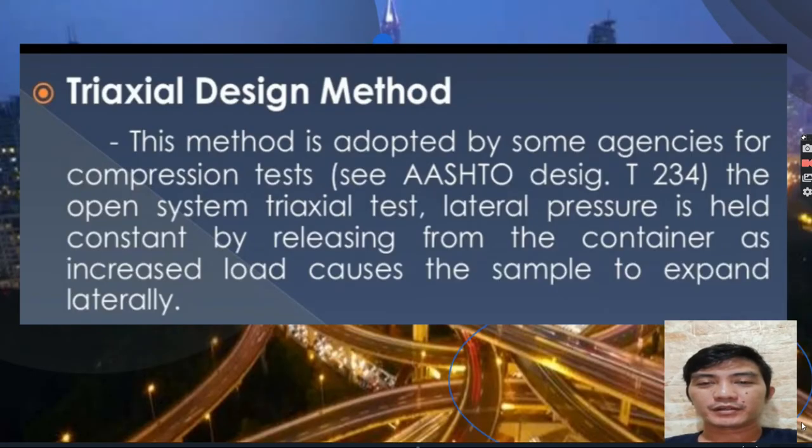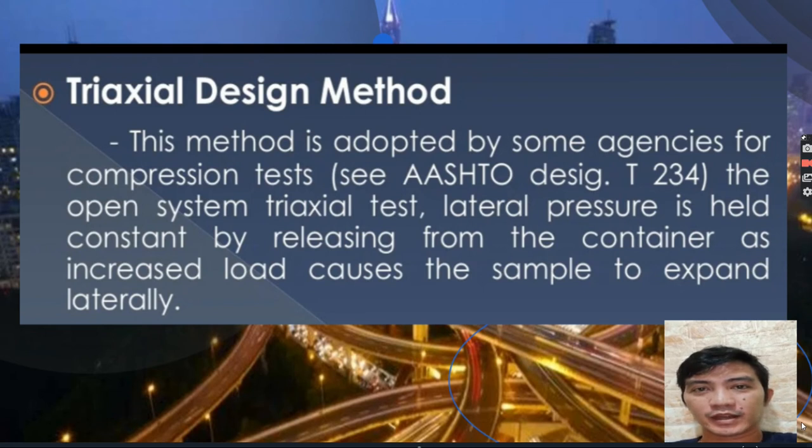Triaxial design method. This method is adopted by some agencies for comparison tests. In the open system triaxial test, lateral pressure is held constant by releasing fluid from the container as the increased load causes the sample to expand laterally.